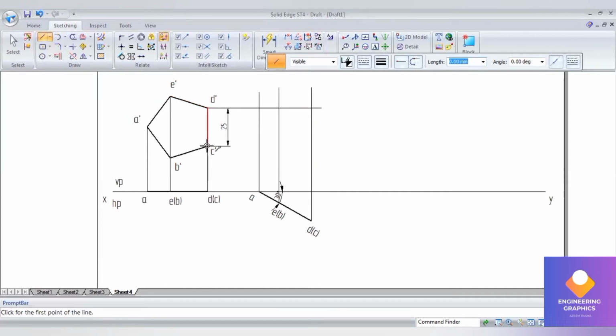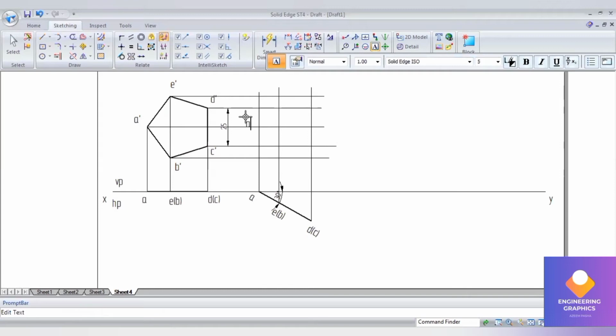Horizontally also you draw the projection lines. From each corner end you have to construct the projection lines. Now write down the notations properly. Wherever the top view and front view projections intersect, you need to write down the notation properly with respect to each end. Now we can join all these points with a thick line. So connect it.